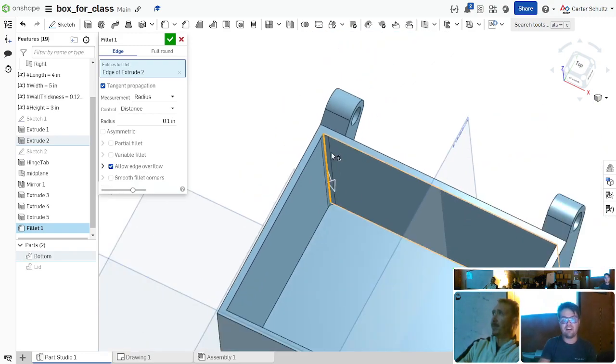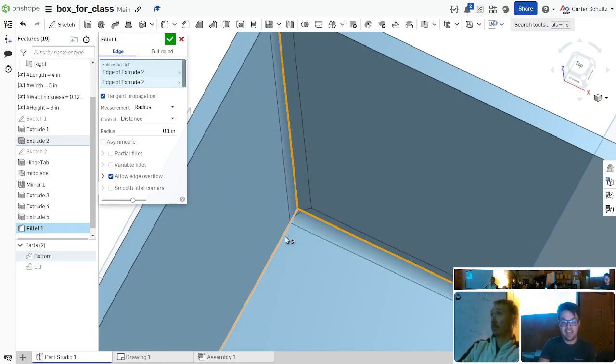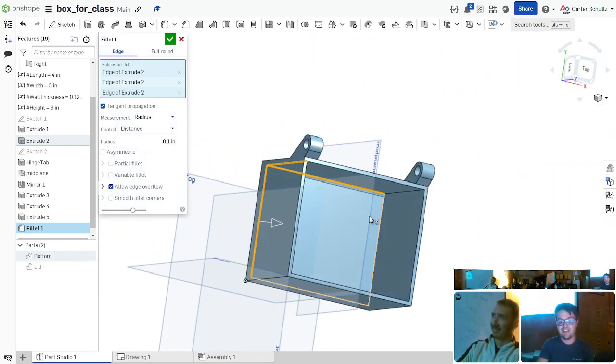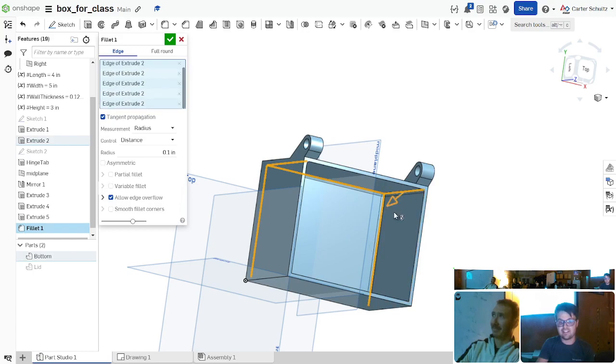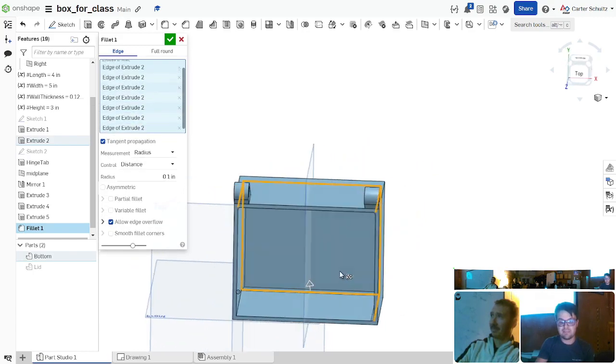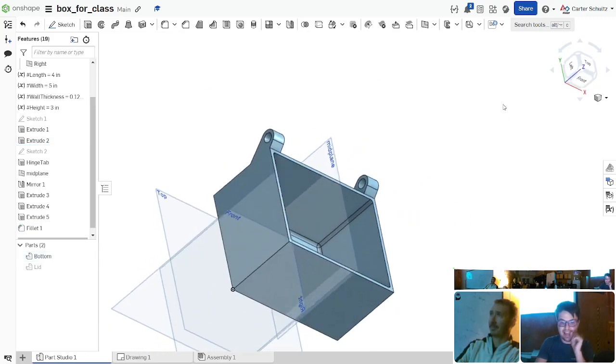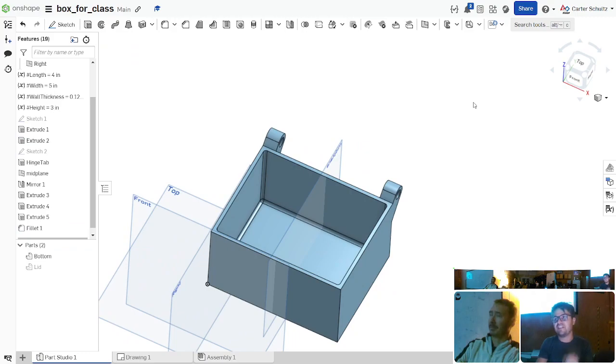That alone wouldn't be very fancy, but if I click on this edge and I click on this edge, then it makes a really fancy 3D blended surface at that corner. And just going in here and clicking all these fillets lets me do cool things. Now, one of the things that I hate is fillets in CAD, because fillets in CAD are the thing that break the most when you go back and change other things. Like, I'm going through and selecting all these individual little lines. If I go and make a little kink in the box, the fillets will break.